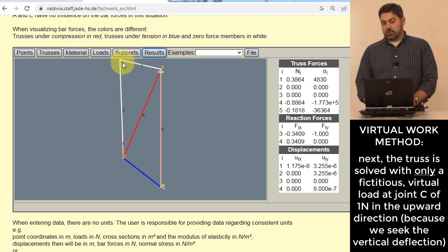Yeah, think about this joint up here, right? Now we have no loads being applied to this joint, right? No external loads applied to the joint. If we have either an X or Y load in either of these members, they cannot react against the other one, right? You're going to end up with an unbalanced load if you have any load at all. You can tell that just by looking at that upper left joint, right? So that makes sense to us. We only have loads in these members right here.